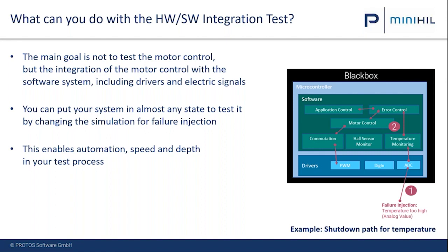But in the end, what I really want to make sure is that we get as an expected effect that the PWM is off after 100 microseconds in this case. So we want to make sure the motor really is off in any situation we have an error. And on the other hand, I want the correct CAN message to inform whoever is interested about the error situation in this motor. So it's a real black box test in this case.